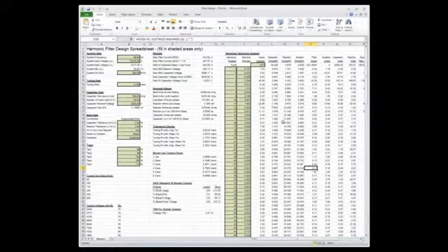But I use this on the side myself so that I can specify a tuning point and generate the actual amount of VARs to put on, the CAN rating, the voltage rating, and also the ohms per phase for my reactor based on actual capacitor units rather than specifying a total sum kVAR. Oh, wow, nice. Yes, so I'll supply this to everyone. On top of it, there are a couple other things if you look in this spreadsheet.